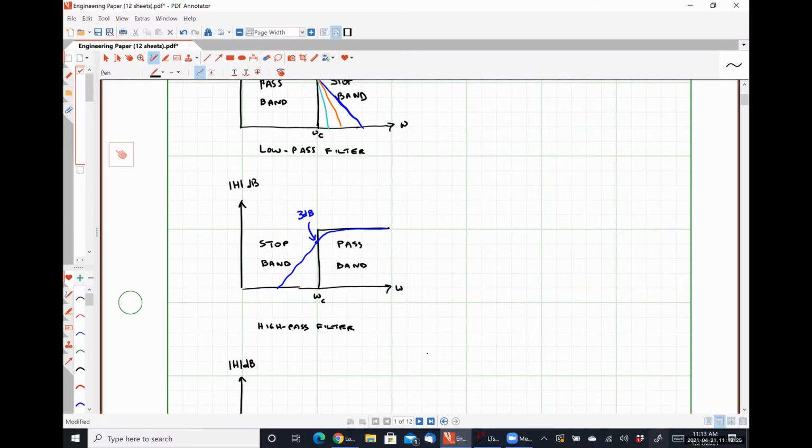It all depends on how high you want your output versus how small your input is. So it's hard to say this is the upper maximum and this is the lower maximum. I will say that when you're designing filter circuits, you're really looking for like negative 60 decibels of attenuation for saying that the signal is entirely killed.